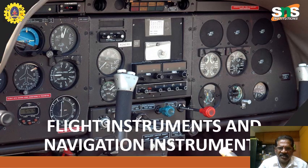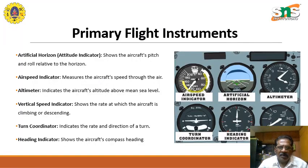There are the flight instruments and the navigation instruments. A general picture has been given, showing how cluttered they look, and each one has its own function in front of the pilot. We have the primary flight instruments. The artificial horizon or the attitude indicator shows the aircraft's pitch and roll relative to the horizon. Airspeed indicator measures the aircraft speed through the air. Then the altimeter indicates the aircraft's altitude above the mean sea level. Vertical speed indicator shows the rate at which the aircraft is climbing or descending. The turn coordinator indicates the rate and direction of a turn. Heading indicator shows the aircraft's compass reading, where it is heading.